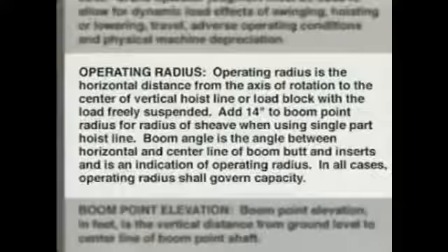Load balancing techniques can vary depending on the load and how it's being moved. Extremely heavy and odd-shaped objects often require multiple lifting points or pick points to spread the load and avoid overloading one point. These types of loads often require the use of special rigging equipment such as spreader beams and lifting beams. In some cases, equipment comes with lifting connectors such as lifting lugs or eye bolts already attached to specific locations to help ensure a balanced lift.